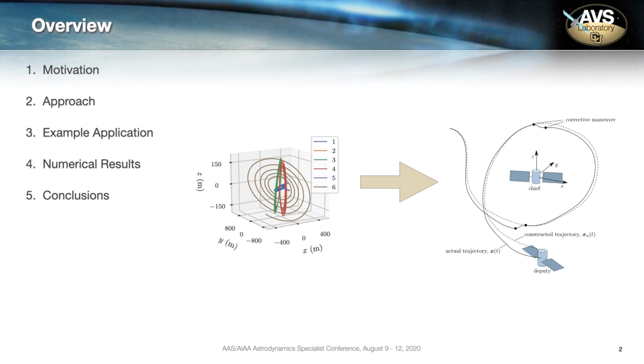Conceptually, this work is about taking the relative motion dynamics in the case of nearby, slowly varying, or quasi-periodic orbits and applying some transformations to obtain a dynamically similar system for which the motion can be decomposed into fundamental modes seen here. Some further analysis isolates which of these motions are persistently reflected by the true dynamics, and those motions are used to construct a desired trajectory in a linear fashion.